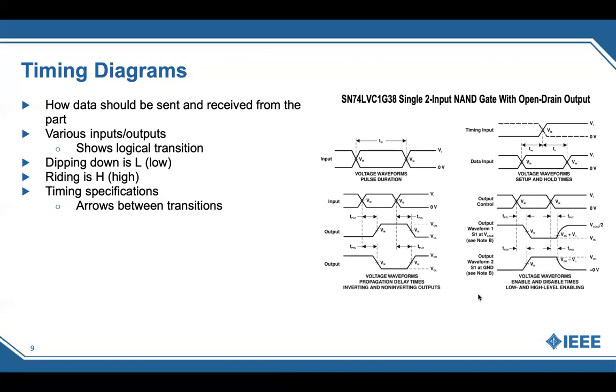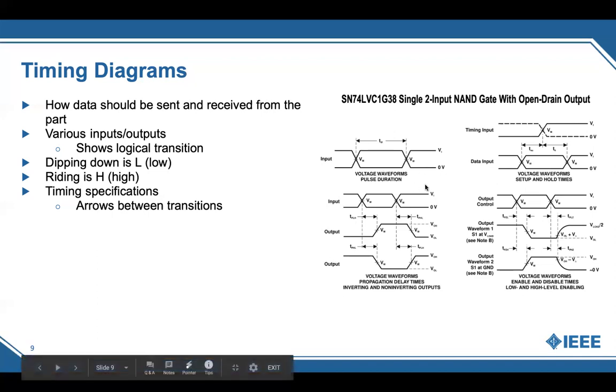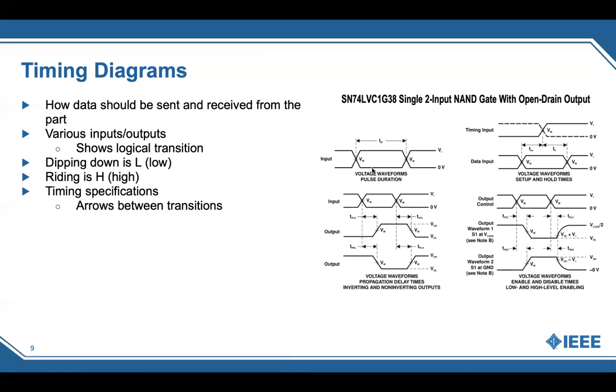And here we see 4 different timing diagrams. And like we said, when the line is going down, it means you're inputting from high to low. And if it's rising up here, you're going from low to high. So it might help if you're trying to see how the behavior would change for your chip itself.